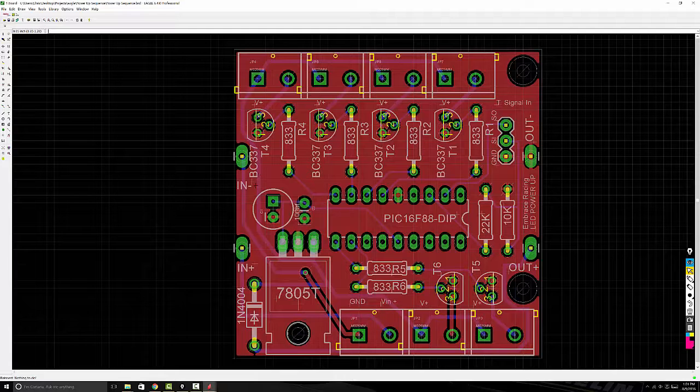And you can faintly see the blue lines in the background. They're the bottom layer. But the red plane will be where all of the ground connections are made. So I really did need 2 layers for this board because there are a ton of ground connections. But for the traces, I organized the board in a way such that for the most part, all of the traces are on 1 layer.